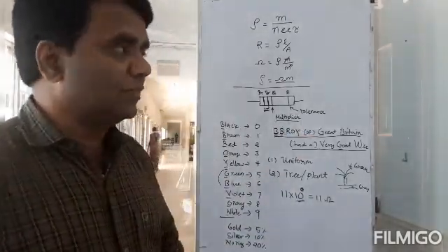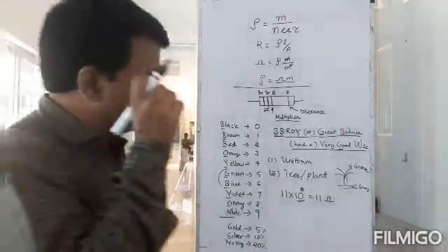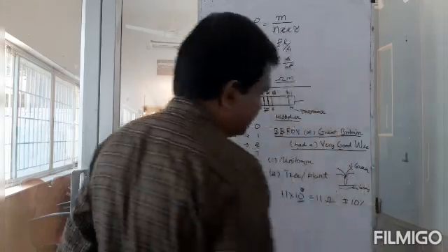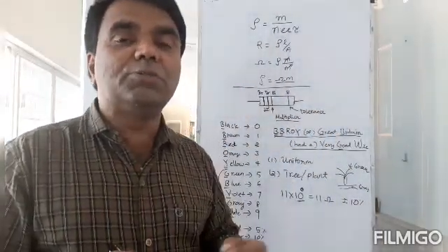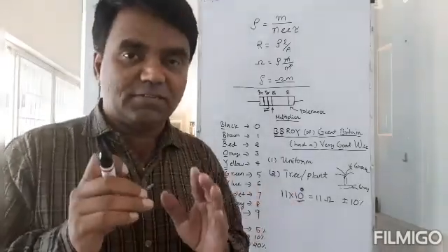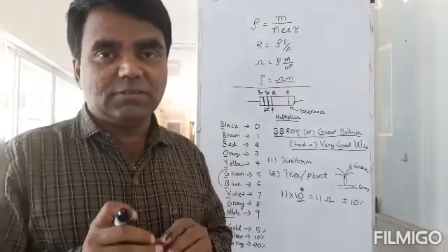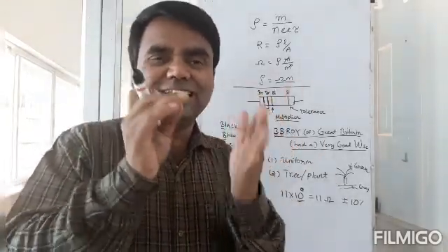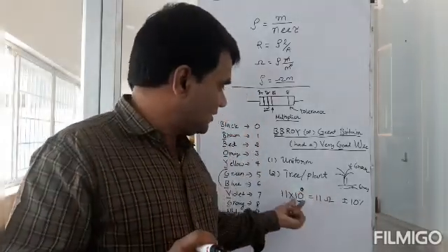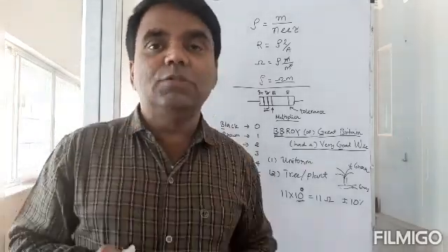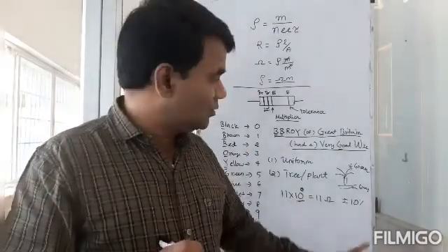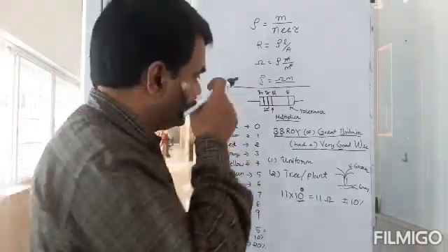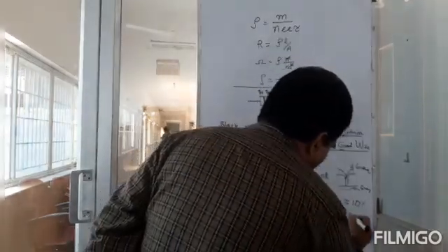Then what about this tolerance level? Silver. I said silver will have 10% tolerance. What does it mean? It's plus or minus 10%. It talks about the quality with which this is made. See, nobody can make exactly 11 ohms. It's difficult to make exactly 11 ohms. There will be some changes, right? Nothing can be perfect. So what they say here is that our rating is 11 ohms, but it can vary within 10% of the stated figure. So 10% of 11 is 1.1 ohm, right?